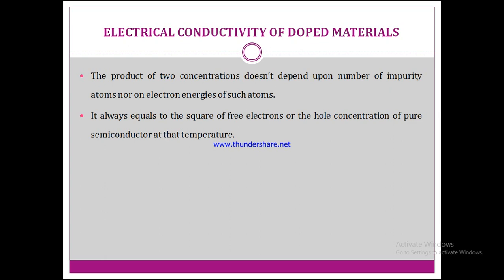At medium values of temperature, the conductivity of impurity type semiconductors decreases to some extent depending on the percentage of added impurity. The behavior is similar to that of metals. This happens due to the reduction in the mobility of electrons and holes.